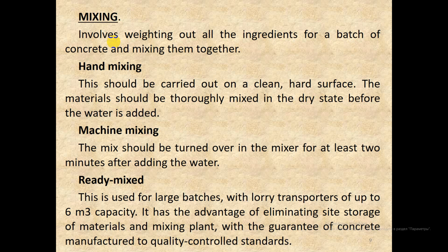Machine mix should be turned over in the mixer for at least 2 minutes after adding the water.